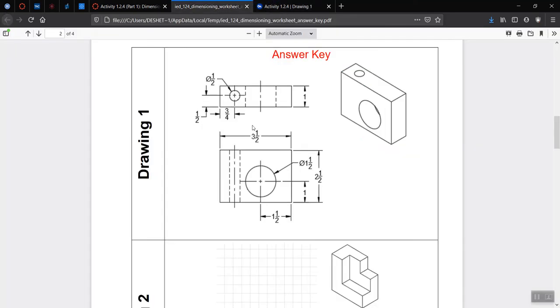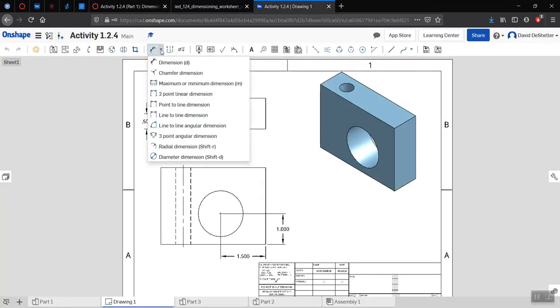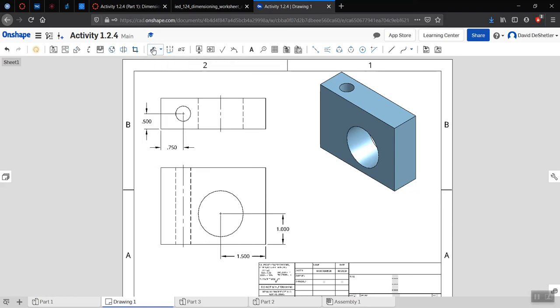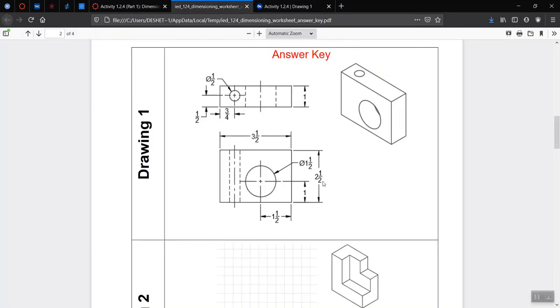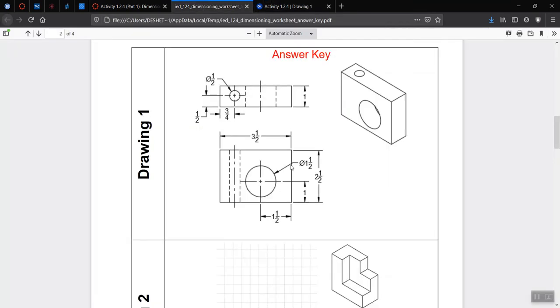Okay, let's do the diameters of our holes next. So I just want to see something real quick here. It should automatically select the dimension for the most part for a circle. If I select the dimension tool and I hover over a circle, it should give me a callout that has, there you go, the diameter dimension on it. Same thing with this circle. It looked like they tried to sneak it in right there on their version. See? Yep. I think ours is showing decimals, theirs shows fractions. We're okay. We're not going to worry about that.